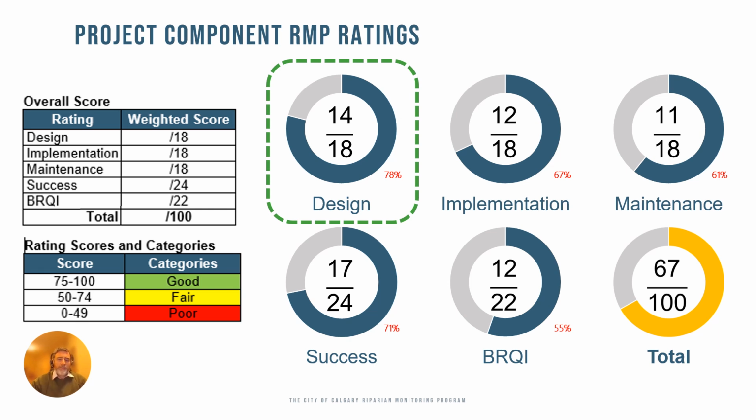However, some sites had lower ratings due to limited design information, issues like erosion or inadequate site-specific design approaches, such as missing toe protection, unnecessary synthetic matting, or discrepancy with the City of Calgary design guidelines on scheduling, stock handling, soil amendments, and road and fencing.